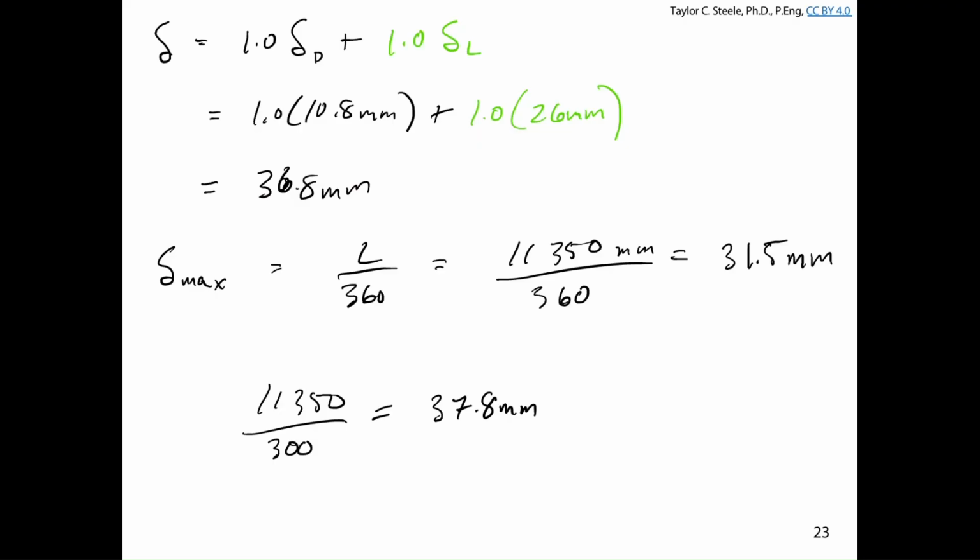I would expect probably, you'd have a live load reduction factor because, again, we're assuming that the probability of that area getting covered in live load is probably pretty small. And that joist is long enough, right? 2.127 meters by 11 and a bit meters, that'd be more than 20 meters. So you probably have a small live load reduction factor of maybe 92% or something like that. So possibly. Good question. Anything else?